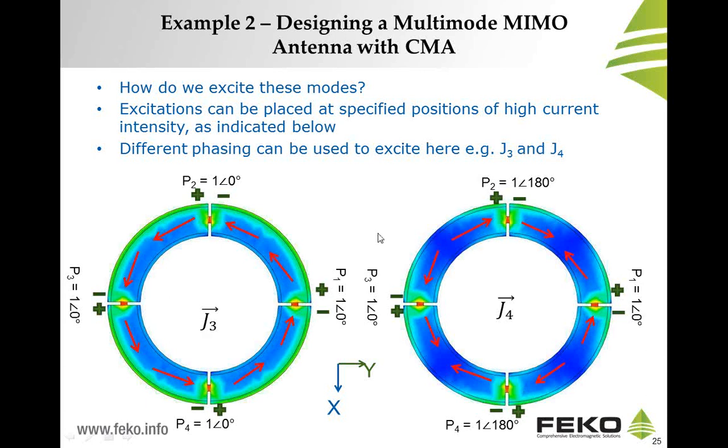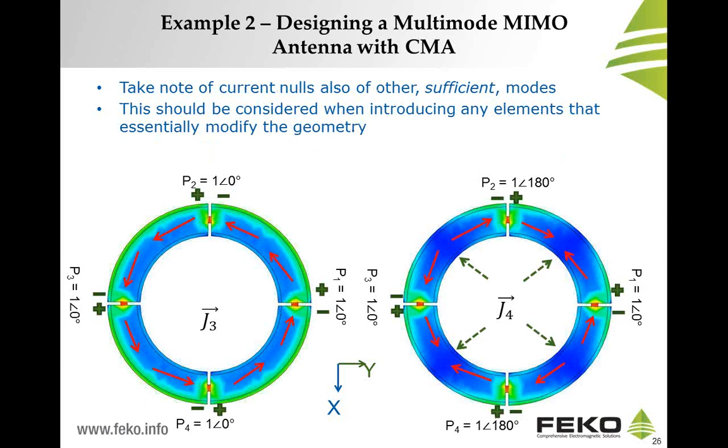Now, let's go back to how we are going to mitigate the effect of this inductive mode. If you can recall from any engineering undergrad course, the way to counteract inductive behavior is to add some form of shunt capacitance. But we can't just go about adding shunt capacitances everywhere because we might alter the behavior of other modes. Characteristic mode analysis also gives us useful information on where to start modifying structures without disrupting the behavior of other modes.